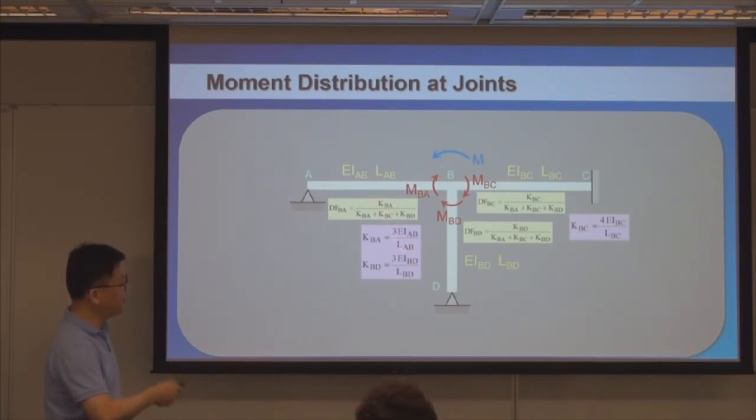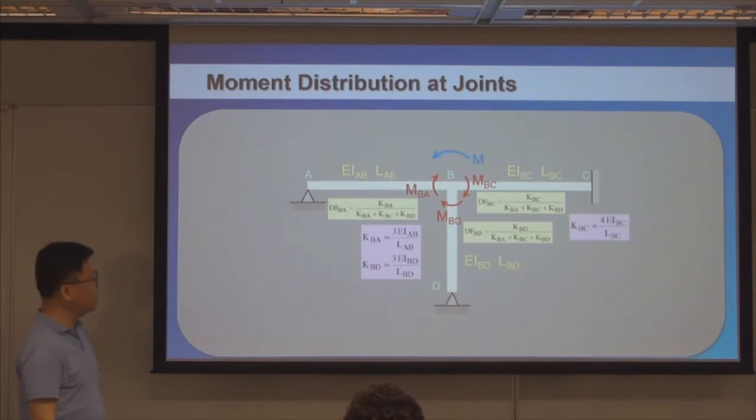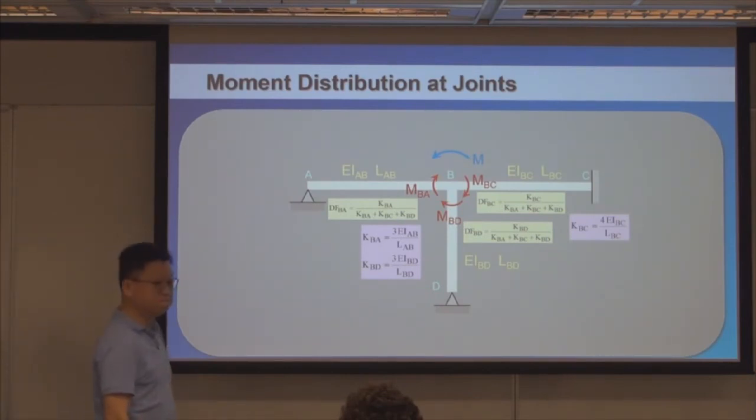for all three components. And then you directly take the external moment here, multiply individually, and then you get the end moments of the components. Isn't that nice? Very easy, right? You don't need to worry about the rotation angle if you don't want to know it. That is a more direct way to get the end moments.